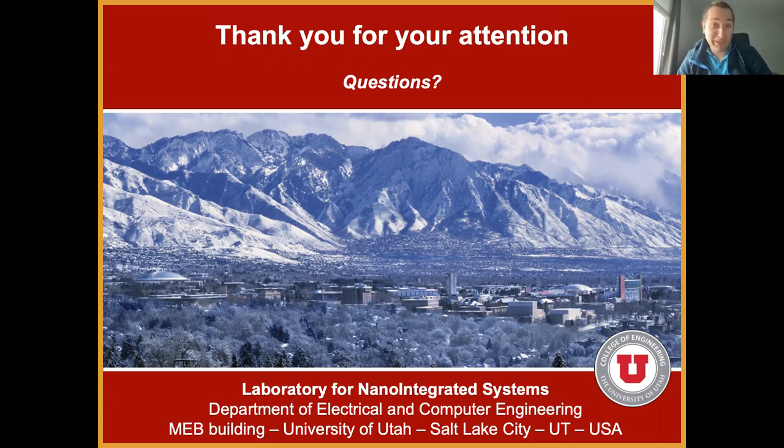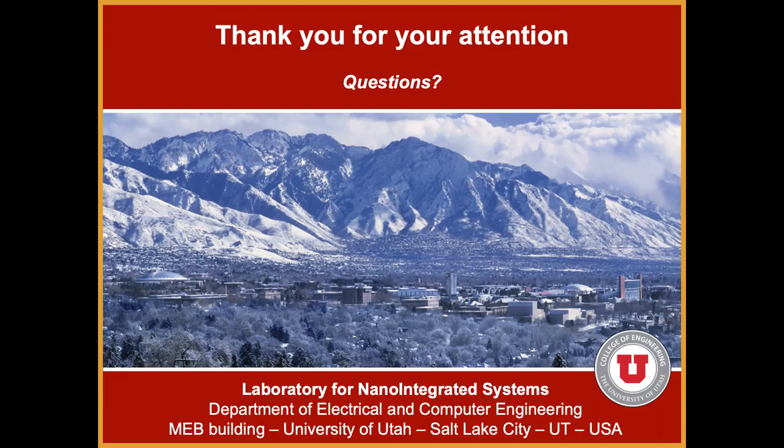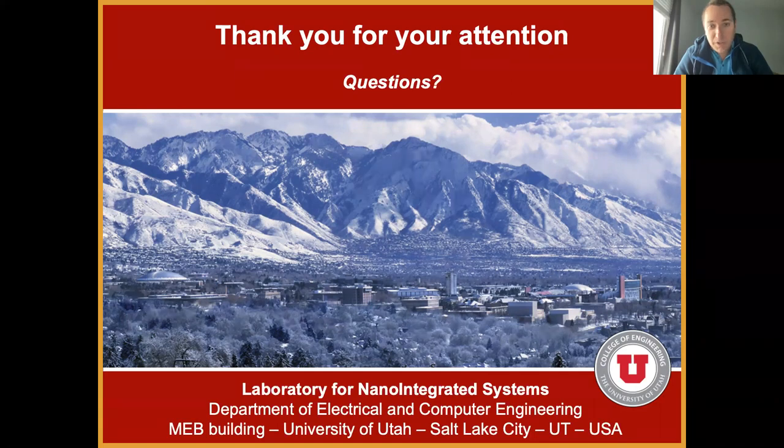This is a very complex question, Jose, and I'll try to be as clear as I can. OpenFPGA integrates as part of its flow Yosys for behavioral synthesis. As a matter of fact, it also has a Verific front end for SystemVerilog and stuff like that, which we're currently implementing and putting in.